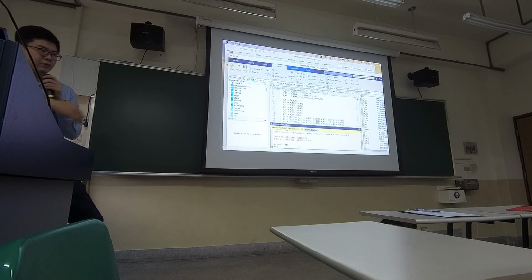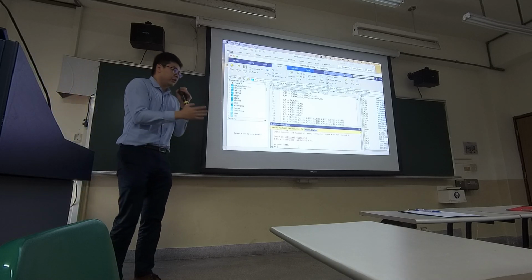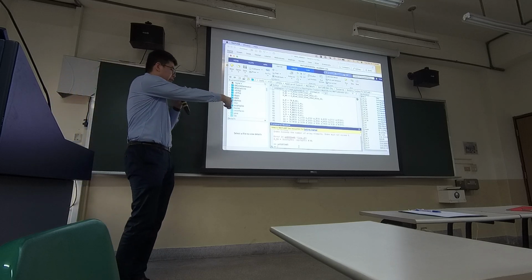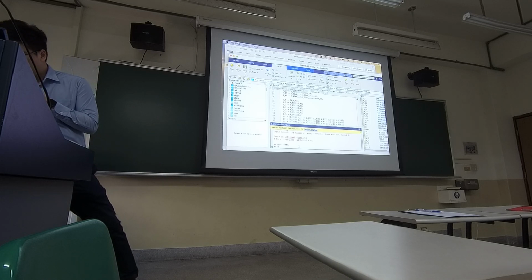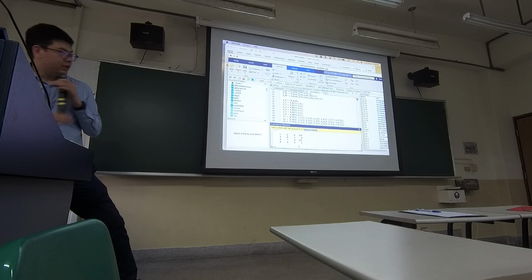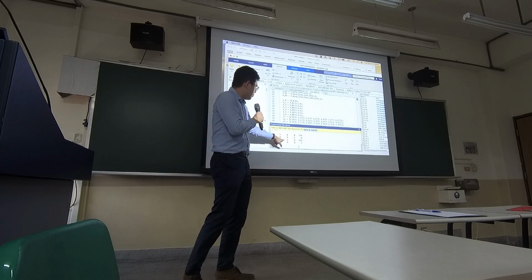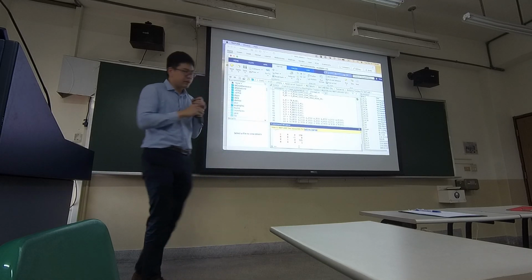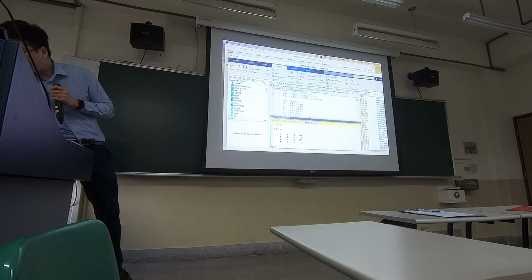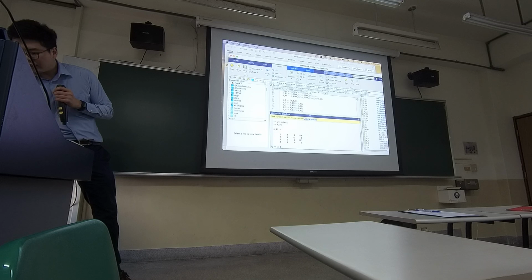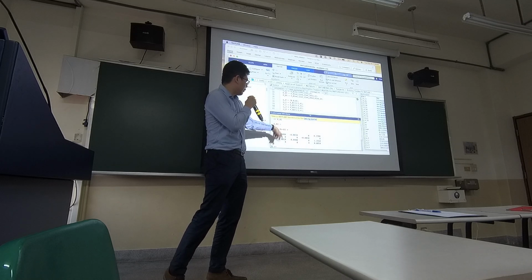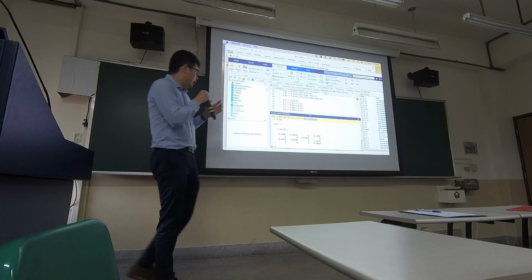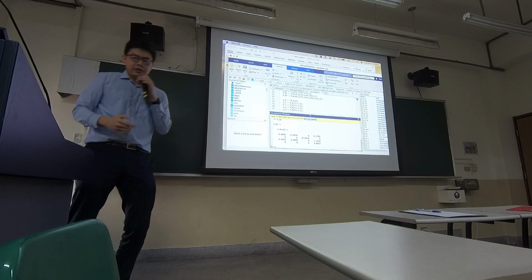And by the way, if you want to check whether your transformation matrices are correct, you can check all the matrices. Like if you want to check the first matrix, you can check whether the coordinate system, the orientation, and the position are correct. And you can also check the second one. So by checking this transformation matrix with the geometry of the robots, you can check your answer.